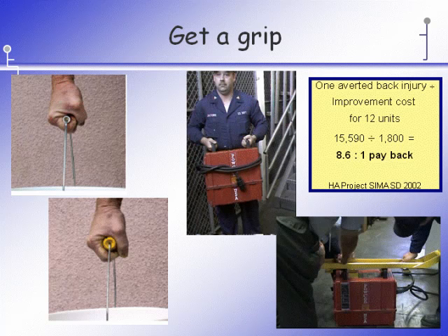We'll see in hand tools that the appropriate diameter for a male and a female's hand is between 1.5 to 2 inches, and that is basically the size of the handle that people are holding on to. So increasing the diameter of the handle makes it much more comfortable for this person to carry the load, as well as the picture on the bottom.